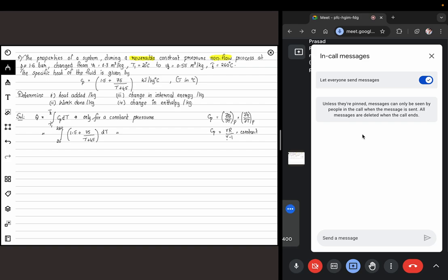As your temperature increases, the contribution of the vibration and other components to the overall internal energy will increase. That will actually change your value of Cp and Cv, so it then becomes a function of temperature. This is one of those types of materials that we are discussing here, whose specific heat is varying with temperature, unlike the ideal gas in which Cp is a constant, not a function of temperature.